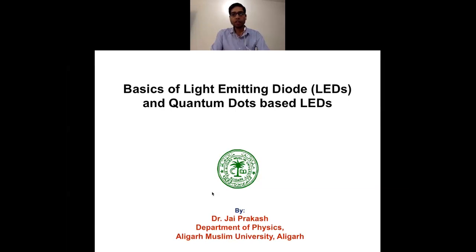If we talk about the applications of quantum wells, then they can be used as active semiconductor lasers, which enjoy widespread commercial use in optoelectronic applications, ranging from high power sources for medical therapy, material processing, and laser printers. They can also be used as pumps for solid state lasers. Quantum wells can also be used in photodetectors, modulators, switches, etc.